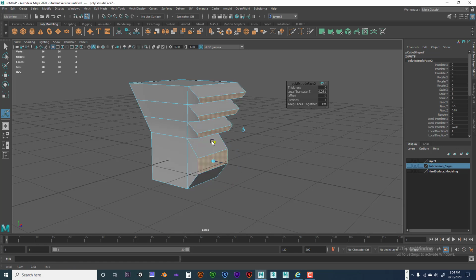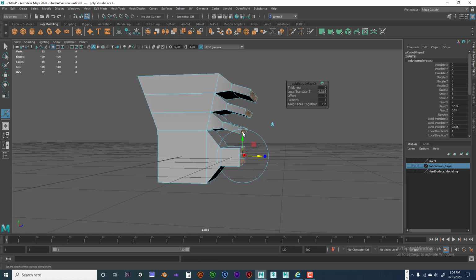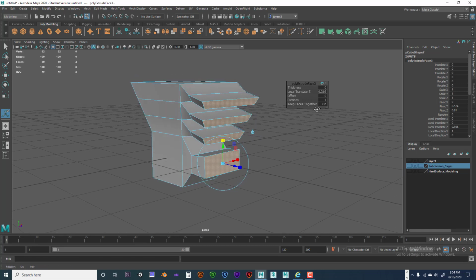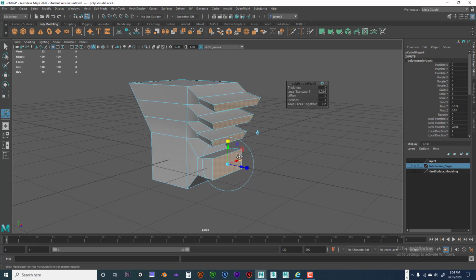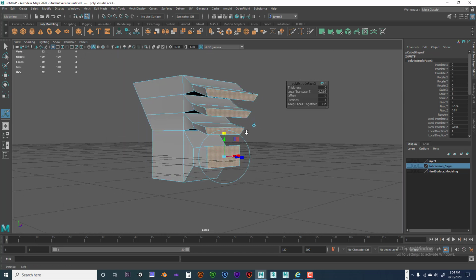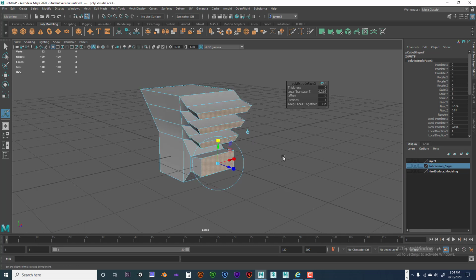And so these will be separate, and can create 4 separate pieces, divisions, and you can continue to extrude those if you want to, and continue manipulating those. So that's really powerful. So that keep faces together tool makes a difference. If you want to keep the faces together to create your object, it really depends on what you're trying to model. Right, on to the next tool.